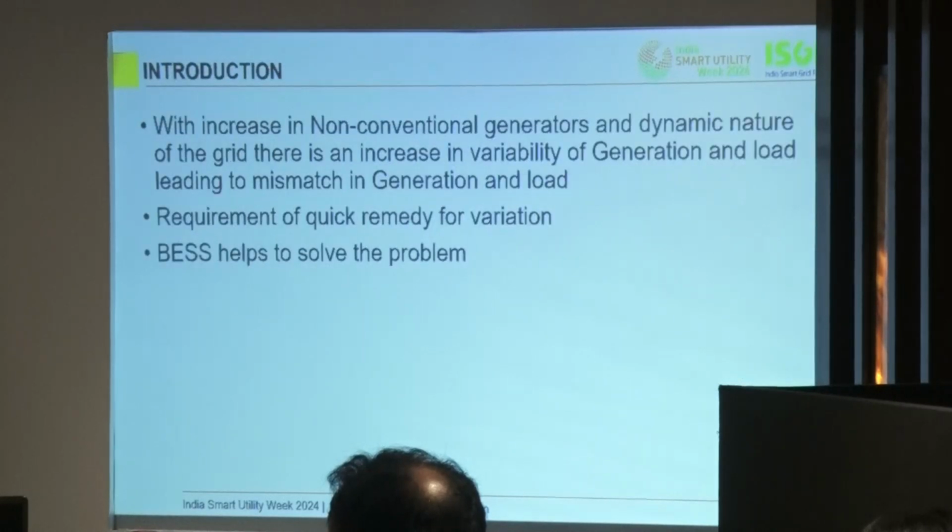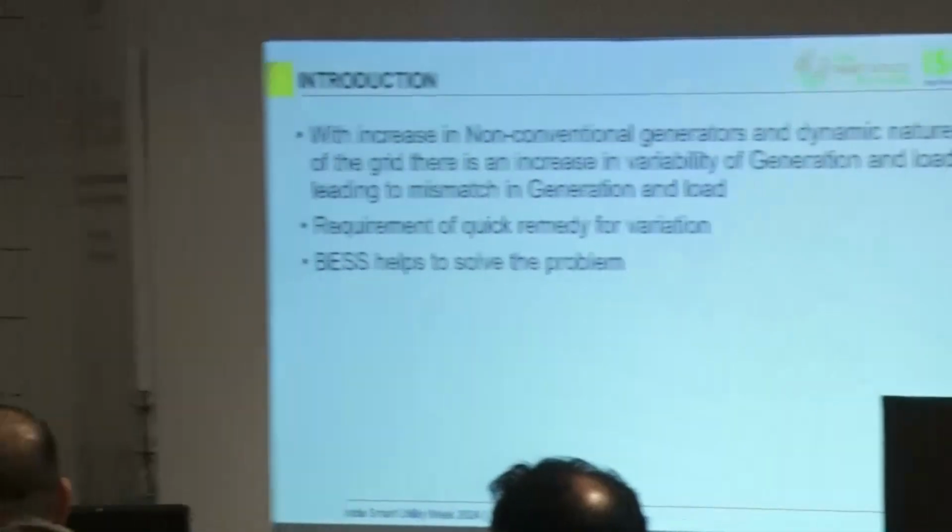So to address the power mismatch, the concept of BESS was introduced. As you know, it can be controlled autonomously, but we integrated it and enabled our software to control the BESS with the same software with which we were controlling the other generators. The background of this GDC software is a component called AGC, automatic generation control.